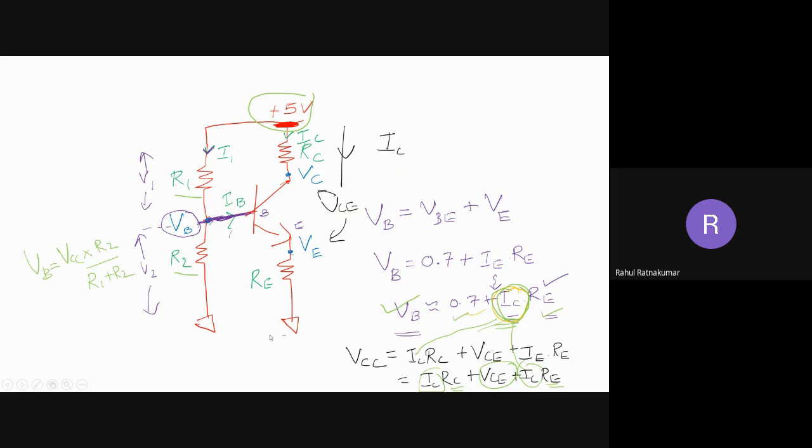Now I'll see what will happen if I give an AC signal to the circuit. Basically, what I'm trying to give is a small, fluctuating signal. It may not be AC; it can be a small alternating signal, any sensor output. So this is my sensor, and this is fluctuating. I'll give this to a coupling capacitor. A coupling capacitor allows AC to pass to the DC circuit, but doesn't allow the DC to come to the sensor circuit or the AC amplifier.